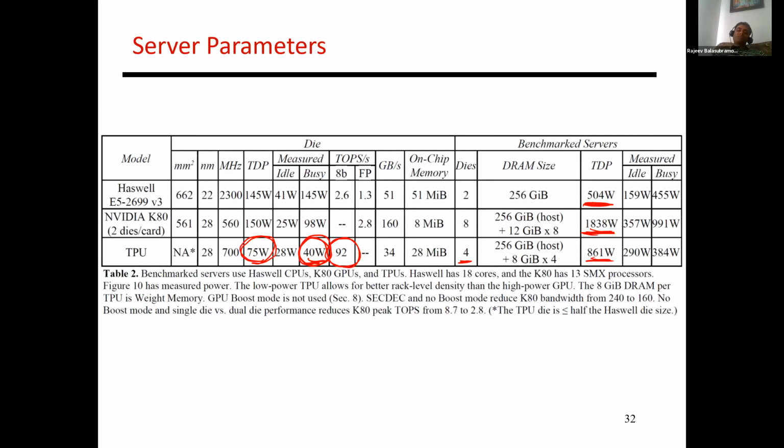So there's this question about spatial multiplexing of a TPU, right? Let me explain what I think you mean by that. Let's say there are 4 different DNNs I need to run, and the TPU is this monolithic 256 by 256 grid. It does not have support to do multiple different DNNs at the same time. To make that happen, you would need to somehow take that systolic array and partition it into 4 different units, each running a different DNN. I don't think that support exists in the Google TPU.